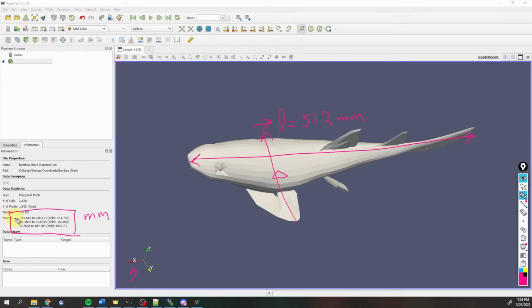But I need to make note of all of these values because I need to create that bounding box, the enclosure, like we did in ANSYS, to make a box around this entire animal. So I'll note these numbers and make a box that's much bigger than this. So we'll go from, say, -800 to 800 and -300 to 300, just to make sure we've got plenty of space around the model so that we don't run into any issues with that limited domain and the boundary layers.